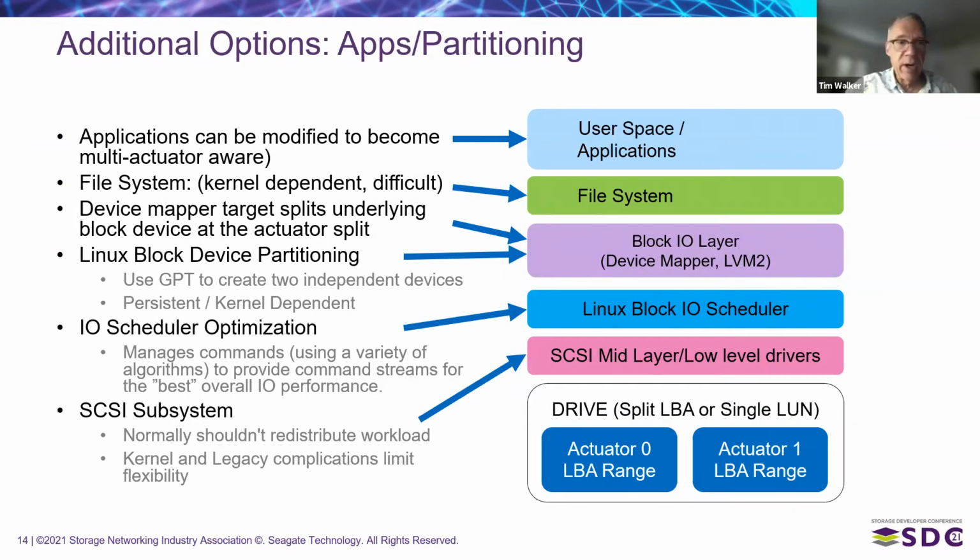Okay, where can you do what? Where can you manage the workload? Because our goal with the dual actuator drive, on the Seagate design that we've been talking about this afternoon, the actuator is pretty much sawed in half, and the upper half of the actuator addresses the upper platters, and the lower half addresses the lower platters. None of the media can be accessed by both actuators. So any particular piece of data that you write on whatever actuator is handling that sector is the same actuator that has to read it. You can't write to one and read from another.